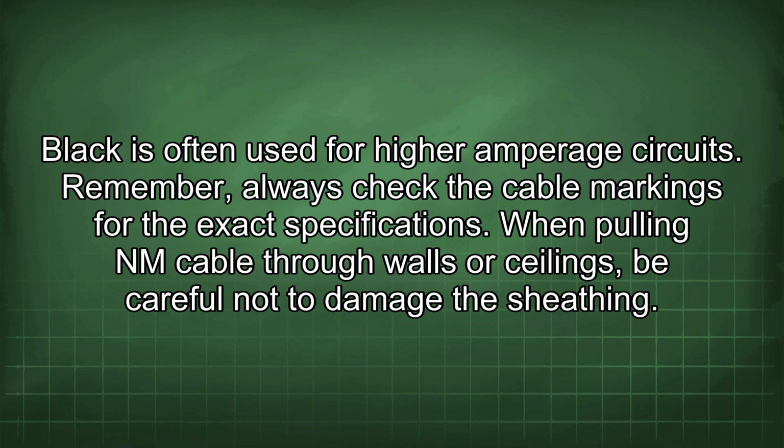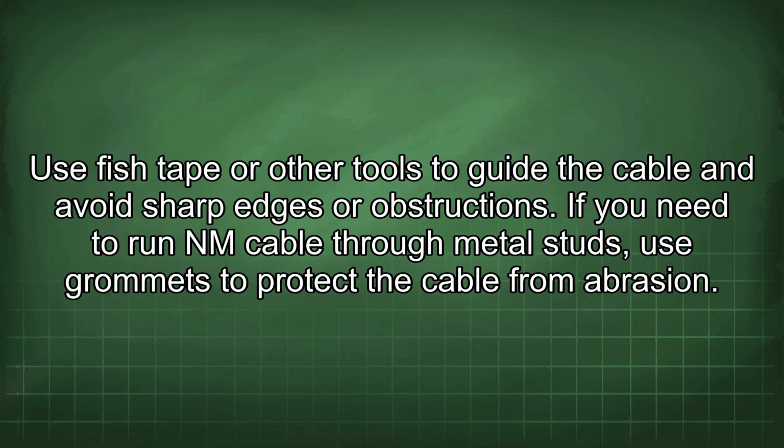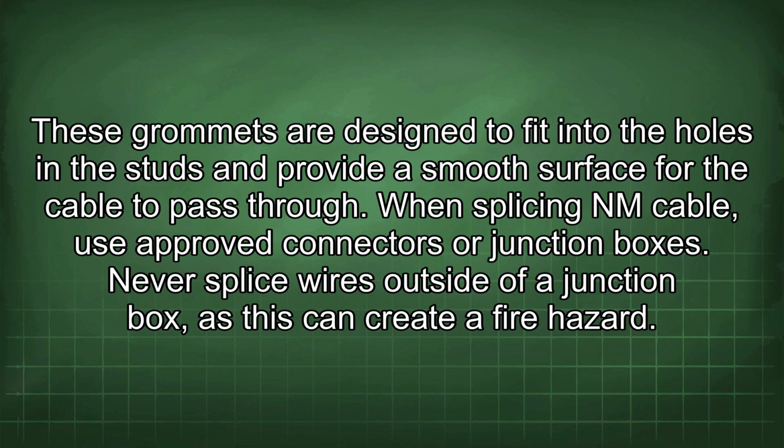When pulling NM cable through walls or ceilings, be careful not to damage the sheathing. Use fish tape or other tools to guide the cable and avoid sharp edges or obstructions. If you need to run NM cable through metal studs, use grommets to protect the cable from abrasion. These grommets are designed to fit into the holes in the studs and provide a smooth surface for the cable